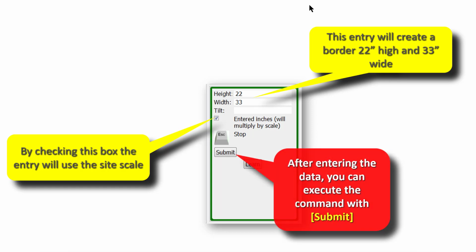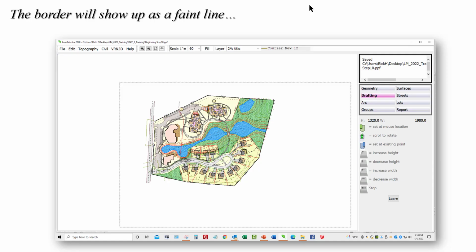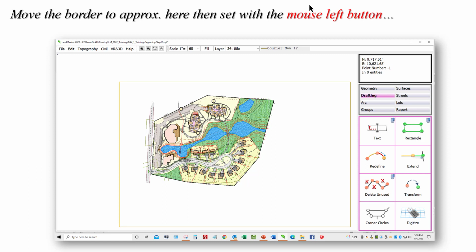Then you'll hit submit, and after that, you'll see a dotted line, a phantom line, show up on the screen, and you'll move your mouse just like you did with text. It's the same type of thing. You could rotate it, but we're not going to rotate it. We have the arrows to increase graphically the height or the width, on the prompt that you see. It's showing the height and the width in feet, and you'll move your title block around, maybe about to here. And then you'll hit the left button to set it.